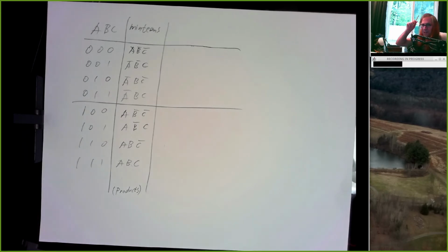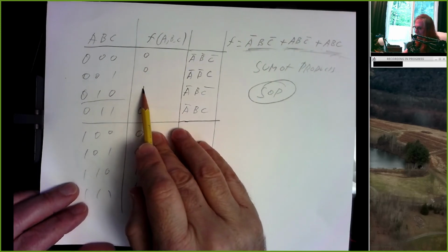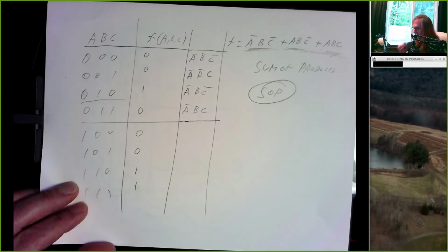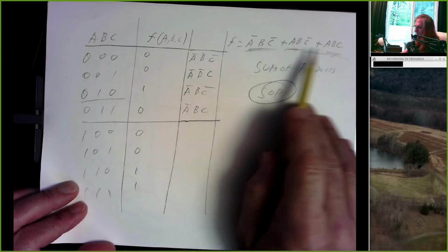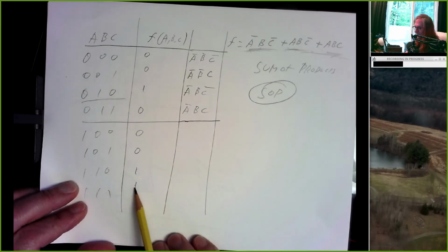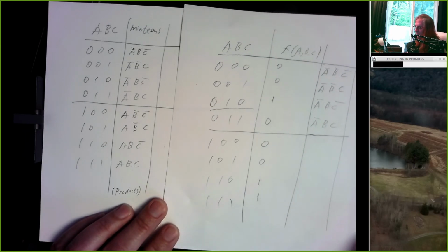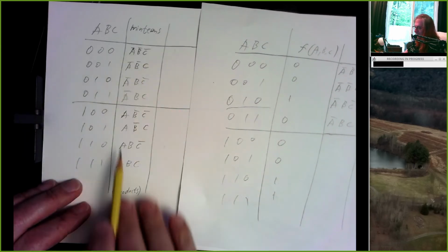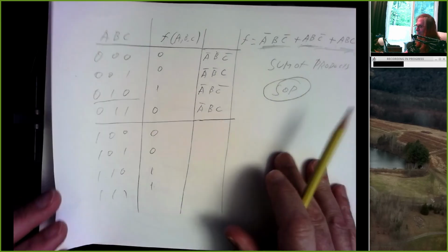All right, think lazy. I have a truth table and I want it to output a 1 here, here, and here. Well, all I have to do is write down the minterms corresponding to each of those rows of my truth table, and I just OR them together. Well, if every engineer knows what these terms are, why should I bother writing them out?